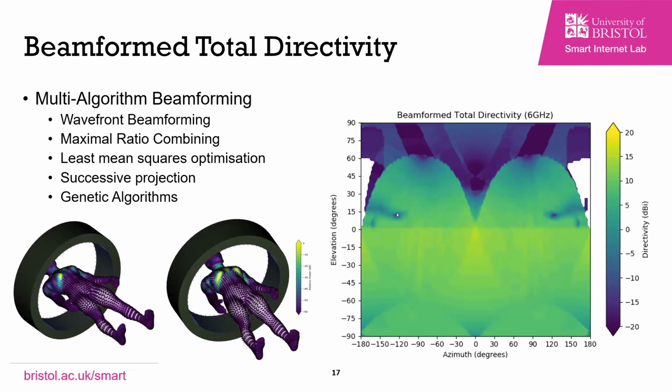All these things can be looked at, whether it's for near field scenarios like medical imaging, as I've got here, or that same UAV, but now beamformed. So this is the total directivity, the main beam directivity, as it steered each one of the possible far field points. And so again, you have this opportunity to look at all the different factors around your design without investing, because at this point, all you've actually got to work with is a frequency, a polarization, and you're looking into different architectures, you're looking into different algorithms, all without doing anything particularly intensive in